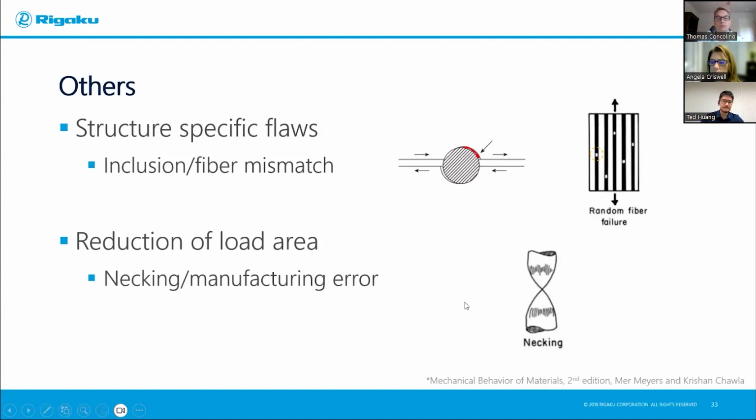So it's called necking. Now, finally, we have some environment-specific flaws, and they still tie back into a lot of things that we learned. Let's say we mentioned a corrosive environment. If you're in a corrosive environment, maybe on the surface you'll have some corrosion pits or corrosion layers with sharp angles. That's basically leading back to the stress concentration concept we've talked about all this time.